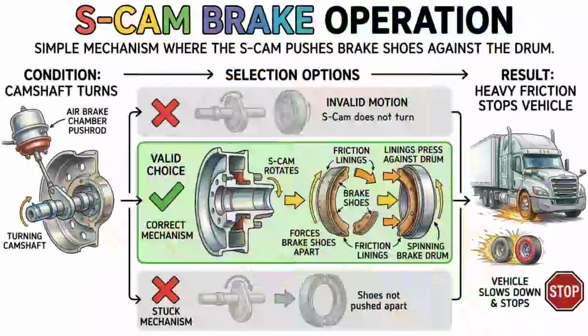The absolute heart of the air brake system is the air compressor, which pumps outside air into the system and pressurizes it. This compressor is connected to the vehicle engine, meaning it only builds air pressure when the engine is actually running. Depending on the design of the truck, the air compressor might be driven by gears or run by belts, which you would check during your pre-trip inspection. The exam will want you to know that the compressor takes normal atmospheric air and crams it into storage tanks to create the high-pressure energy needed to stop.